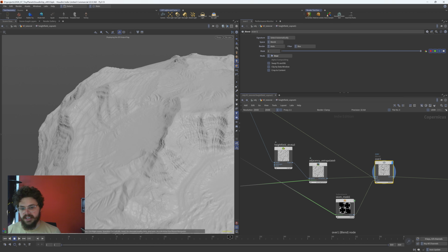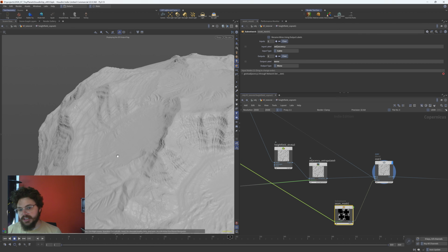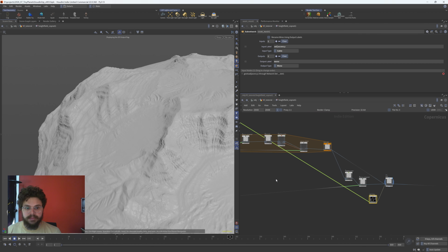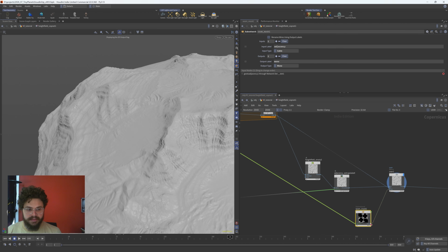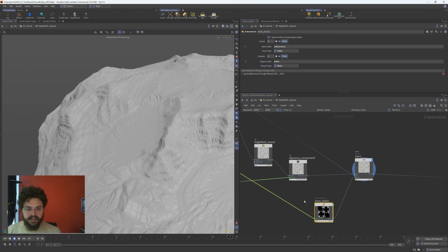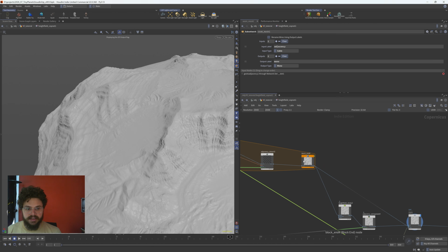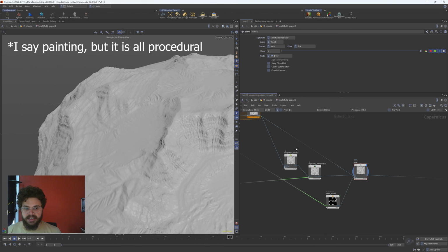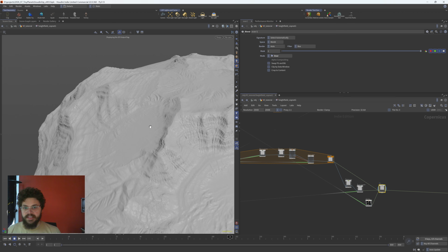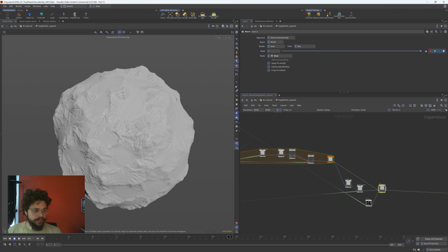And then at the very end, I'm taking my seam mask workflow and just in-painting all of those seams with my seamless terrain again. So I'm going back over to my last iteration here, which was pretty much seamless, painting that in to cover up any of that strata seams. So you can see before, after, or even before, after. And that's the Heightfield. So hopefully this hasn't gotten too long here.